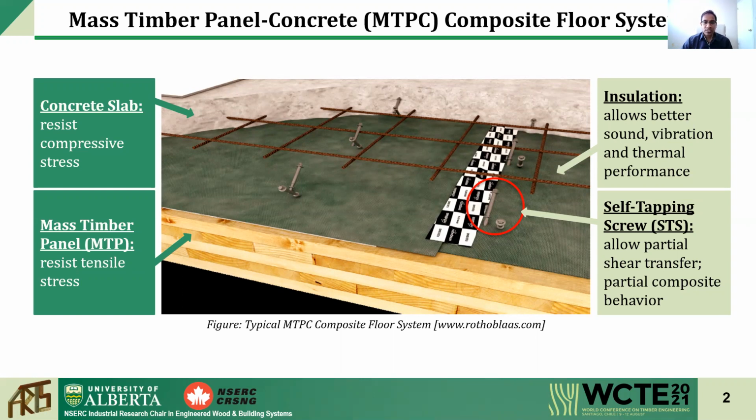Allowable floor span for the TCC system is often governed by serviceability performance requirements such as deflection and vibration, which are directly dependent on the effective bending stiffness.